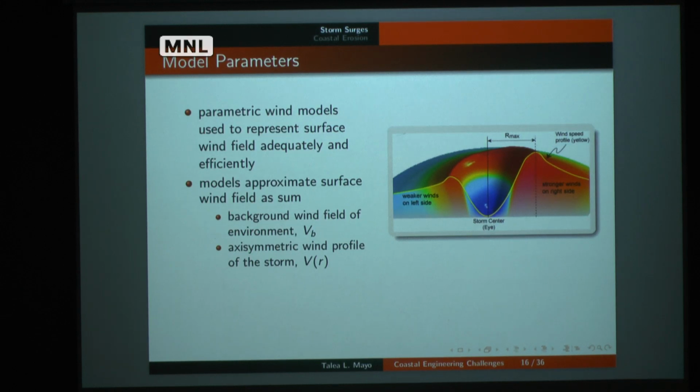So a lot of the work I've done connects because I'm trying to reduce these uncertainties in various ways. One of the publications we just put out was about the parametric wind field in SLOSH in the operational model. A lot of times you're not able to fully represent the wind field of a hurricane if you're hindcasting or forecasting, right? You don't have the wind data everywhere. You have just a few parameters like the maximum wind speed or the radius of maximum wind, the forward speed, etc. For this reason, ever since the 1960s, when people started forecasting storm surges, we parameterize the wind field.